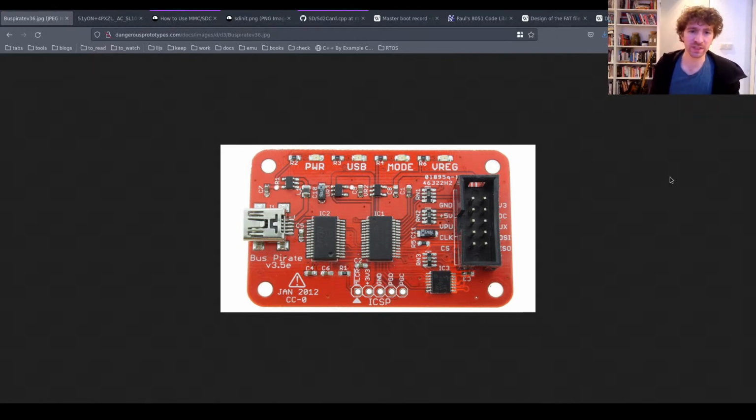But another part of the reason is that with this tool, the Bus Pirate, and with the stack of code I'm building up for it that allows us to easily interact with these kinds of devices, it's basically creating this nice prototyping environment where you can take a device and figure out the communication with that device before you go and implement it in a microcontroller or something for an embedded system. And that's exactly what we're going to be doing today,